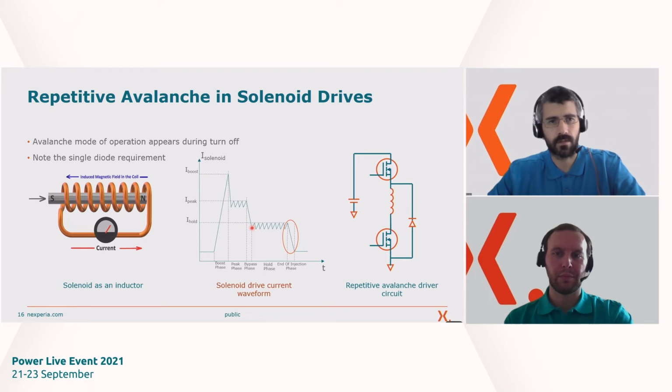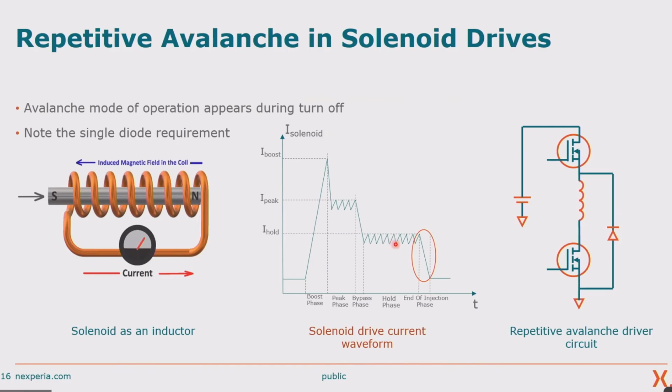And once the core reaches its destination point, a lower amount of current can be applied to hold it at that position. So these currents are regulated by this switching FET, but at the end, the turn-off is actually dictated by the bottom selector FET.